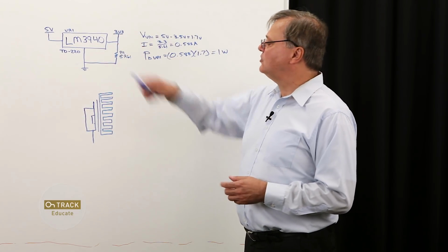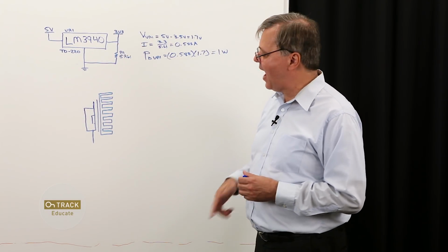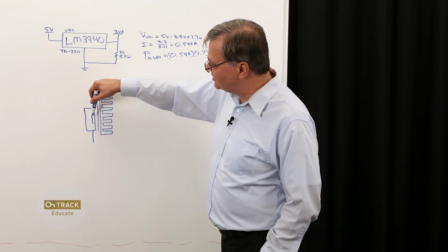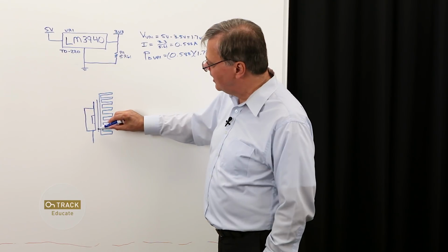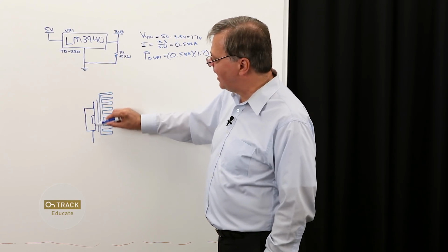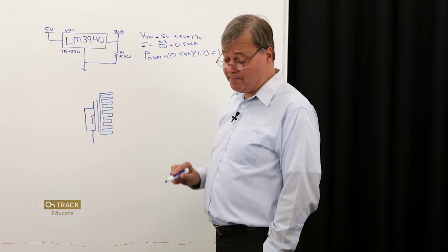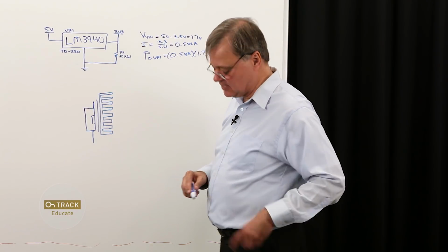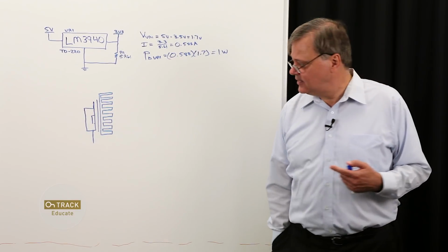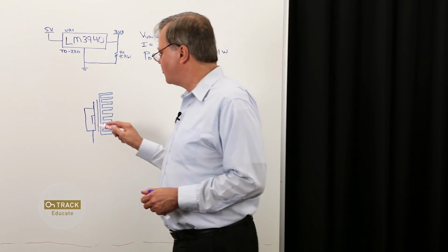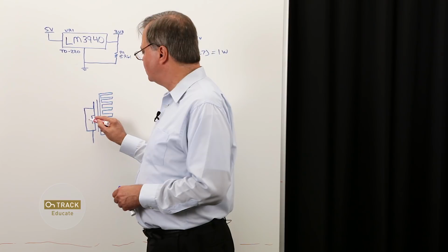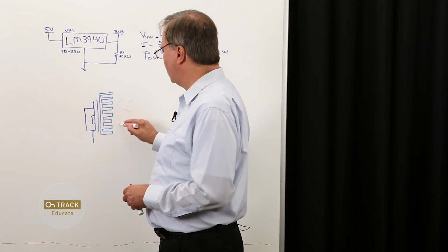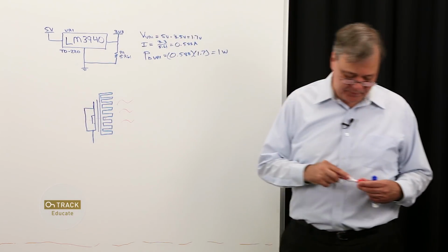Now, our voltage regulator is in a TO220 package, which I've drawn here. So this represents the junction of our semiconductor, and this is the back metal surface of our TO220 package. Then we have a thermal interface material and a heat sink. The heat generated by our voltage regulator is going to flow in this direction and then be dissipated to our ambient environment. Okay?